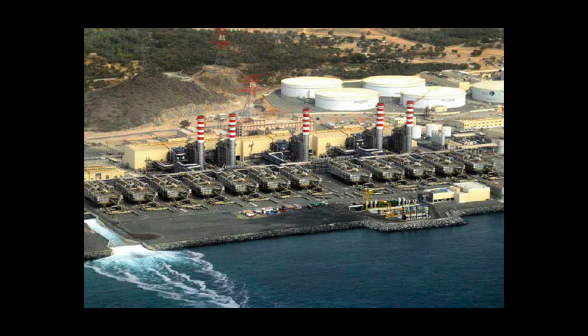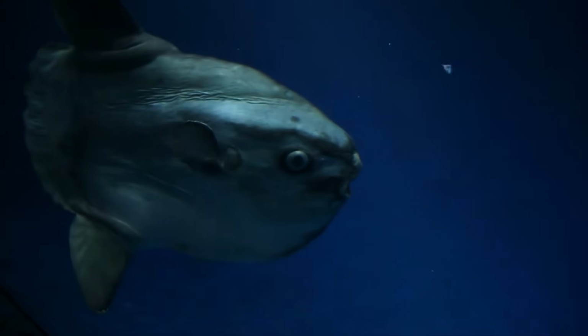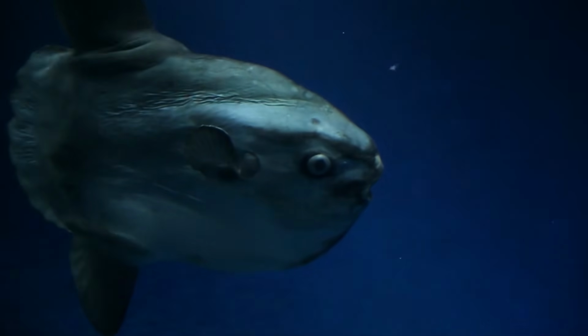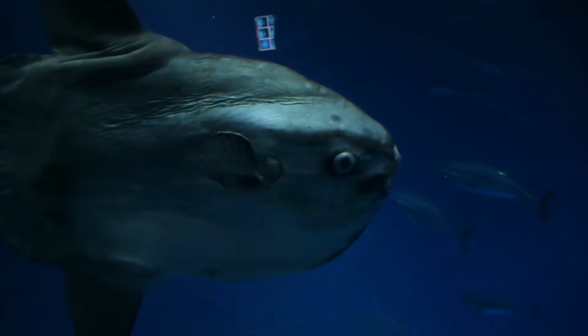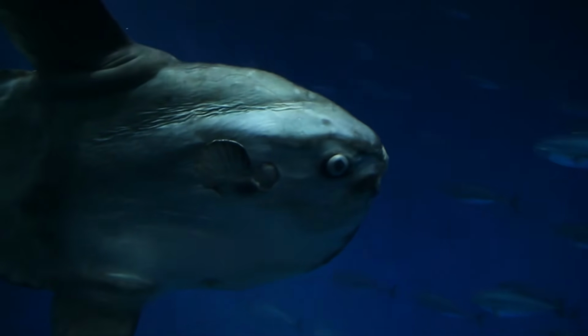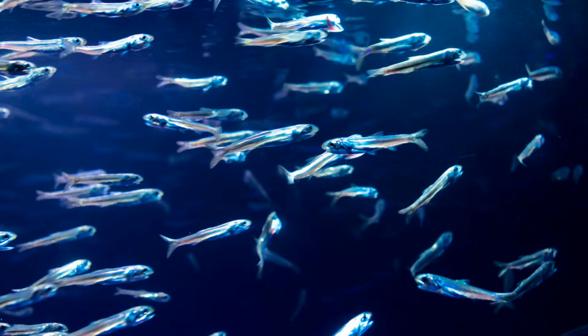Desalination plants need to take in water from the ocean, and that presents a threat to marine and sea life. Fish larvae, eggs, and plankton get swept up by these plants. Examinations have found that up to 10 to 30% of fish embryos are being affected. Obviously, this is not acceptable and has been responsible for desalination plant shutdowns in the past. Engineers attempt to mitigate these with slower volume intake rates, nets, and other barriers. None of these are specific to nuclear desalination, of course, but we should talk about and plan for them.